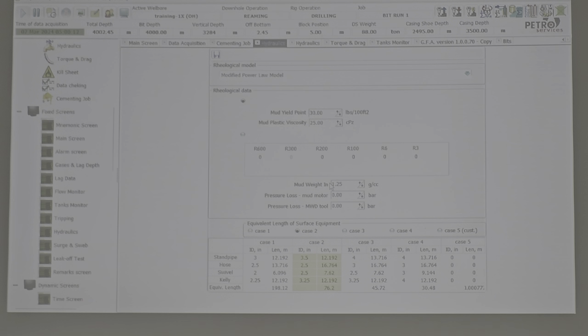So now we know the function of this. We get this data from the directional driller. All hydraulics will be good, including system pressure loss, because sometimes we need this data for evaluating the mud behavior inside, because mud rheology is very critical in deep wells. So they are looking for hydraulics, impact force, HSI, and hydraulic horsepower. These parameters are important in deep wells.